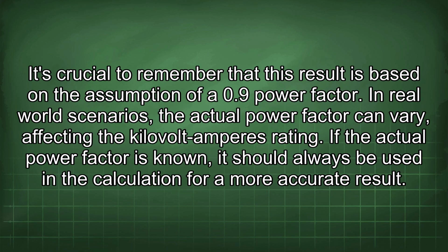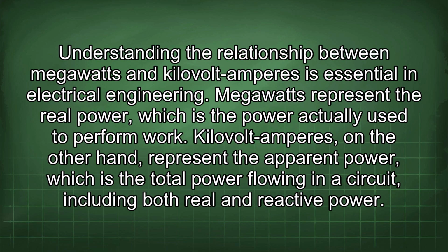It's crucial to remember that this result is based on the assumption of a 0.9 power factor. In real-world scenarios, the actual power factor can vary, affecting the kilovolt-amperes rating. If the actual power factor is known, it should always be used in the calculation for a more accurate result. Understanding the relationship between megawatts and kilovolt-amperes is essential in electrical engineering.